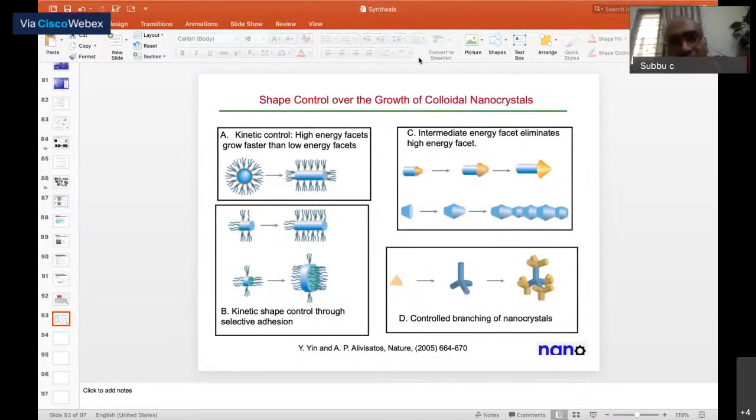But the main problem with the solid state method is that you always need a high temperature furnace. Even though it appears to be very simple, to control the chemistry you need to make the particles as small as possible, try to make it as a pellet, and understand the temperature. You need to understand whether you are operating at a minimum of 2/3 of the melting temperature or not.